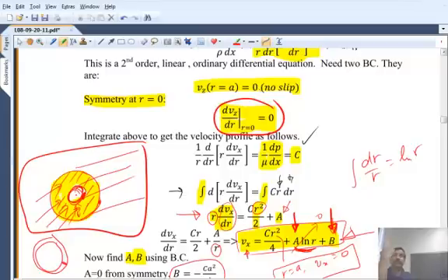Reynolds, who did this experiment in the 1800s, observed from experiments, even before these equations were derived, that the flow was streamlined laminar flow up to 2100, and above that it becomes turbulent. And to answer the question of where it derives its source of fluctuations in the radial and angular direction, it took a long time.